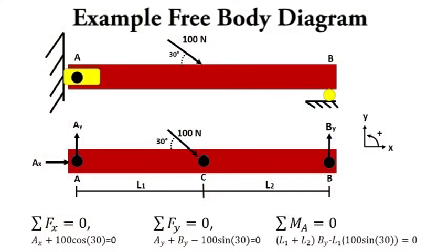Free body diagrams isolate a body from its surroundings and show the effects of these contacting bodies as forces and moments acting on the body you have isolated. Most forces act directly through surface contact. However, such forces as gravity, which is represented by weight, act through a distance without direct surface contact.